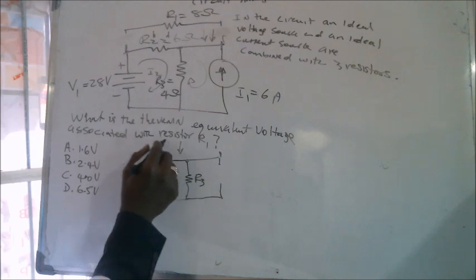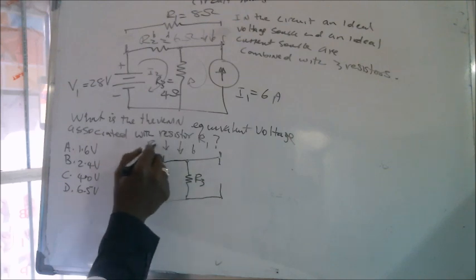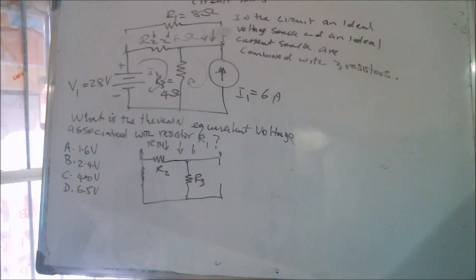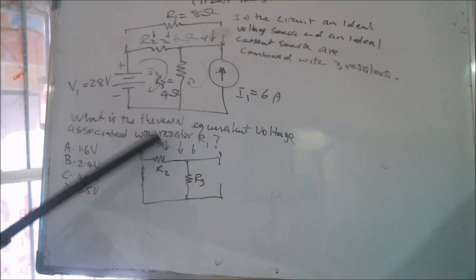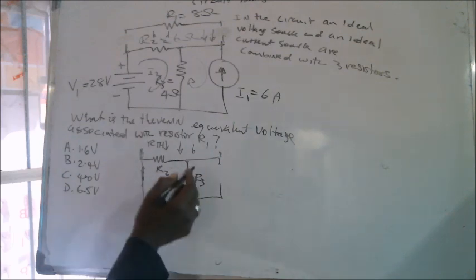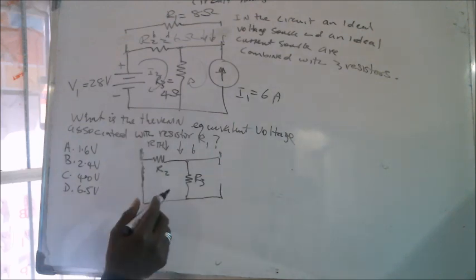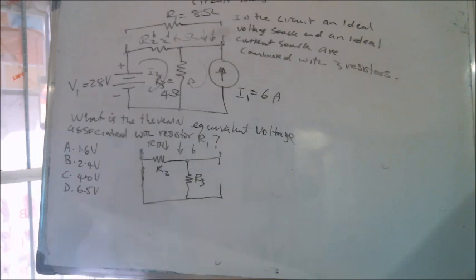And as we say, we're going to isolate the circuit. We're looking in here to find R-Thev, looking at it from that side and removing the 8 ohm resistor, which is considered a load. R1 is considered a load resistor at this point. So looking inside this way, we could calculate R-Thev. What is R-Thev here? If you look at it properly, you'll see that R-Thev is actually 2 resistors in parallel. These 2 resistors are in parallel.